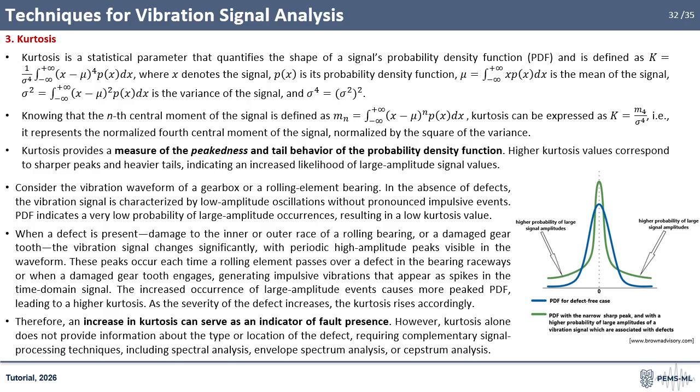Therefore, an increase in kurtosis can serve as an indicator of fault presence. However, it does not reveal the defect's type or location. For that, complementary techniques like spectral analysis, envelope spectrum analysis, or cepstrum analysis are required.